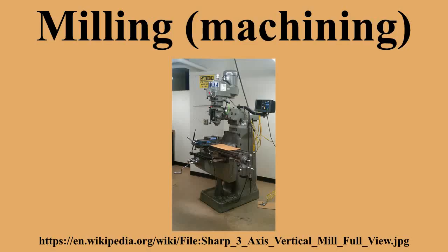Aside from size and precision, the principal difference between these hobby-type machines and larger true vertical mills is that the XY table is at a fixed elevation. The Z-axis is controlled in basically the same fashion as a drill press, whereas a larger vertical knee mill has a vertically fixed milling head and changes the XY table elevation.